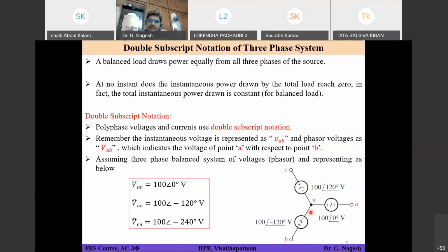In a generator, you will talk in terms of space, that means in terms of angular motion. In a generator with 3 phases, you will have 3 conductors, one conductor in each phase. The first conductor, if you are placing at 0 degrees, the second conductor you will place at 120 degrees. That means phase B. That 120 degrees which you are physically creating as a difference in space will be reflected as 120 degrees in the time domain also. I hope you got it.